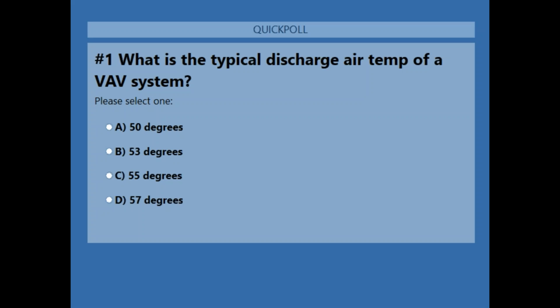While you guys are answering that, I'm going to read a couple other questions that came up. Ferris asks, can a system have a combination set up between VAV boxes and regular ductwork with normal registers and outlets? Yes, you could do that. It would not be advisable, but it could be done. So what he's saying is that he wants to have a couple zones that are essentially wild, and they don't have any dampers to throttle the air back. You could do that, but the problem with those scenarios is that those zones are going to get 100% airflow of 55-degree air all hour long, all occupied hours of the day.